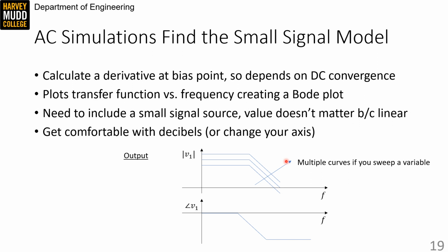Many programs default to reporting AC outputs as decibels, so make sure you refamiliarize yourself with how decibels work, or change the configuration of your y-axes if you're desperate. But Bode plots are so stereotypically log scale that it's generally a better idea to leave it in decibels.